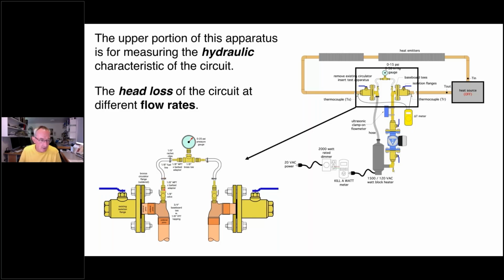Of course, this would be threaded into the valve, and then just use some type of little ratchet clamp, the little plastic ratchet clamps, or you could use a stainless steel clamp of some sort, anything that will clamp that hose onto that barb fitting. We're not going to go to really high pressures here, but something that could withstand at least up to 30 psi. And then we're going to use the same type of fitting along with a T up here, coming in from both sides.